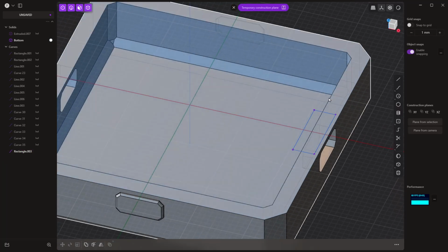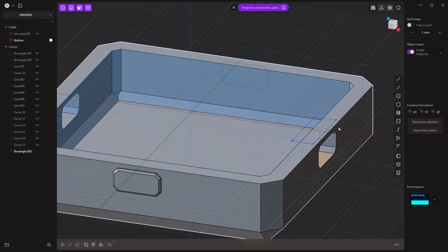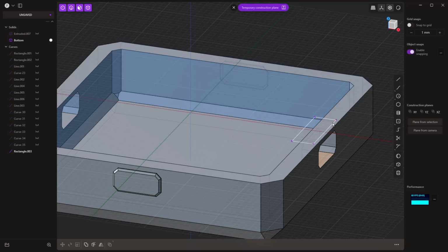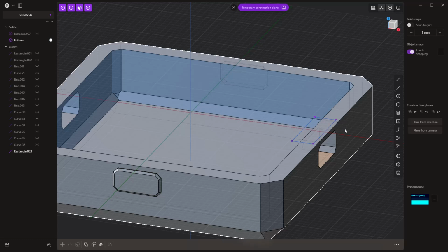Now, printing a thin wall like that could be problematic, but we're doing it for two reasons. One is because we need this thing to help center itself and help deflect it when we're inserting it. And making this section fairly thin will also help us allow that section to deflect a little bit as well. Again, with your own printer, you need to play around with how much material you need in these areas. You may find that printing out a couple of different lids is needed to make that work.